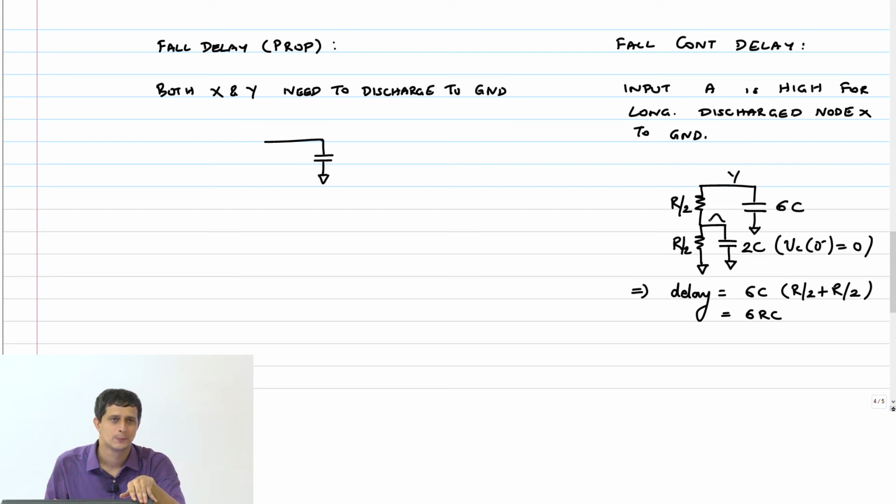Okay. So her question was, if this capacitance was already discharged to ground, that means the VDS of that bottom NMOS transistor is 0. So how can you have any current flowing through that? She is right, because to accommodate some current, the VDS has to bump a little bit, right? Only then you can have some current.